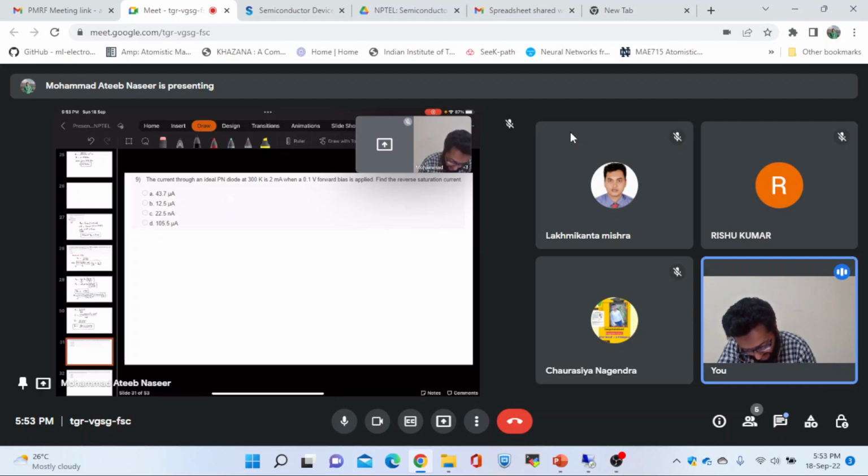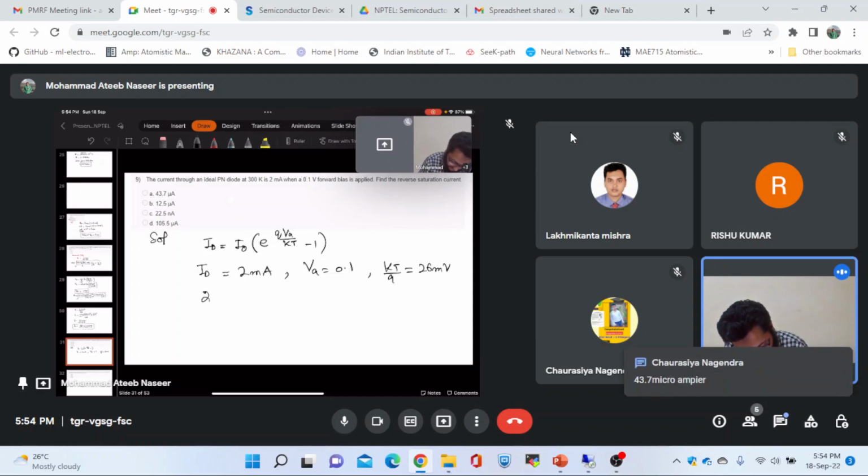तो अगर हम रिवर्स सैचुरेशन करंट कैलकुलेट करने जाएंगे, हमारे पास डायोड की जो इक्वेशन रहेगी, the diode equation will look like the ID is equal to I naught, where this I naught is the reverse saturation current, exponential of Q by VA by KT minus 1. So हमें पता है कि ID हमारे पास है 2 मिली एम्पियर, और जो V applied है वो 0.1 का है, और this KT by Q जो that is given by 26 मिली वोल्ट। सो हम डायरेक्टली सब्स्टिट्यूट करेंगे वैल्यूज। So if we directly substitute now these values, this will be 2 into 10 raised power minus 3. This will be I naught.